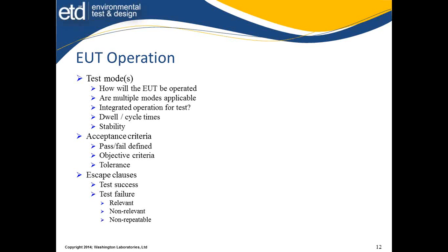Can I turn it off and on at the right duty cycle to evaluate it properly, allow the heat to be cooled off, because it never really operates properly. I seldom see these kinds of things in most environmental plans, the duty cycle. A good designer will look at that because he knows he's going to burn his unit up, but the test lab may not know this.